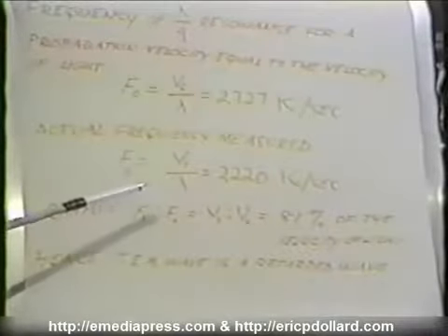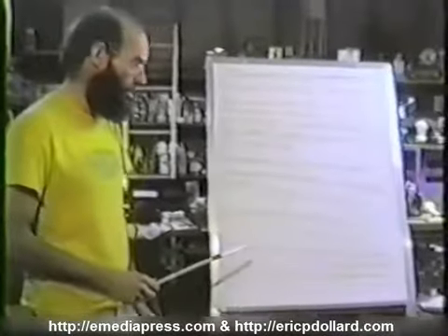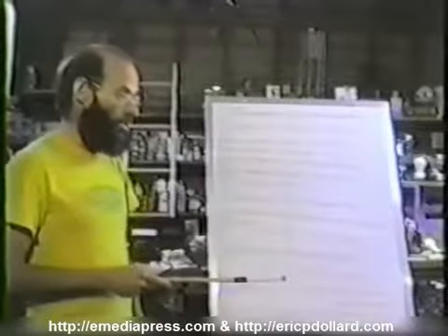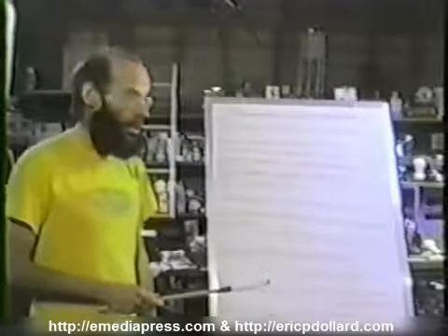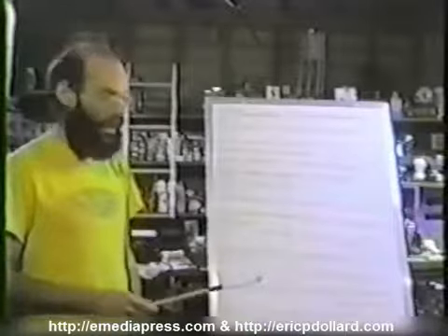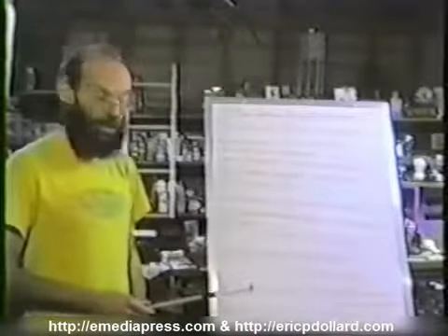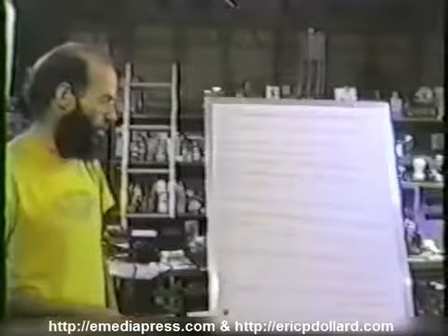Hence, this transverse electromagnetic wave is a retarded wave in that it propagates at a velocity less than that of light. Now, the reason for this retarded propagation velocity is due to the fact that the velocity of light is slowed down by the translucent medium that fills the cable to insulate it, and the resistive losses and conductive losses of the cable in general also tend to slow down the wave a little bit.